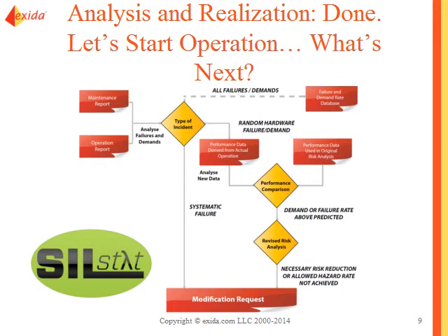But at the same time, they didn't record a single thing for safety instrumented function equipment. So you could say, well, the relief valve data was adequate, but not necessarily for the safety instrumented function. They simply didn't have a means to record this information.